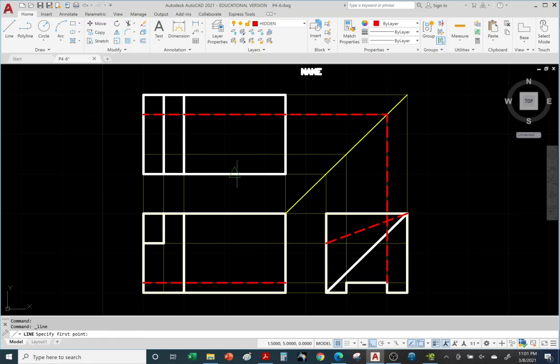Let's do it again on the opposite side. Right side view, left corner this time. Go straight up, hit the 45, go across, and there it is. Right click enter. So here is the tunnel going through the entire length, just like in the front view.